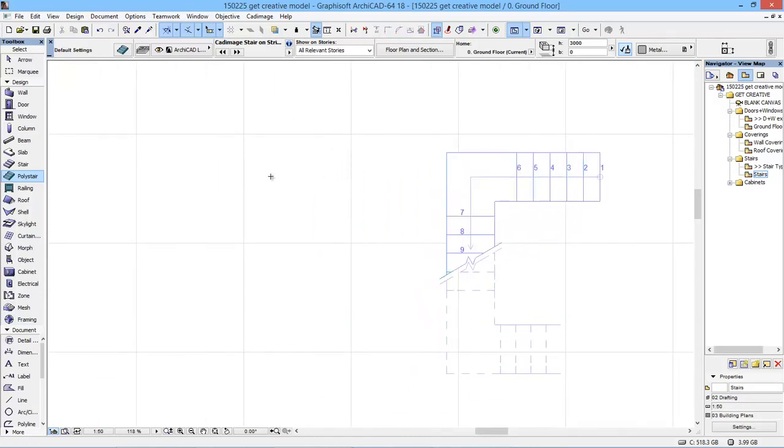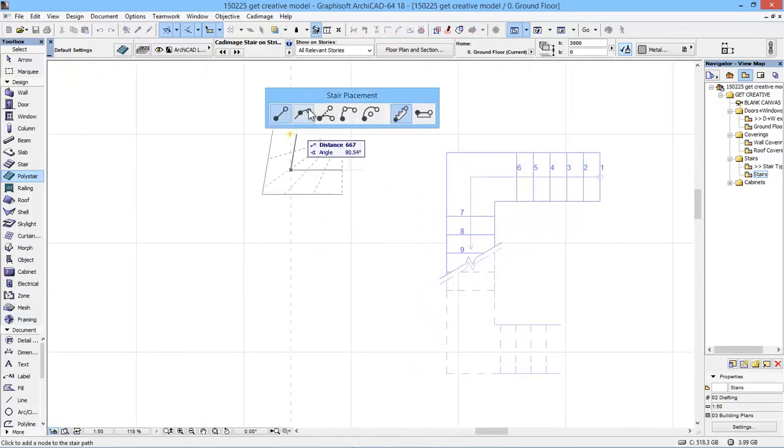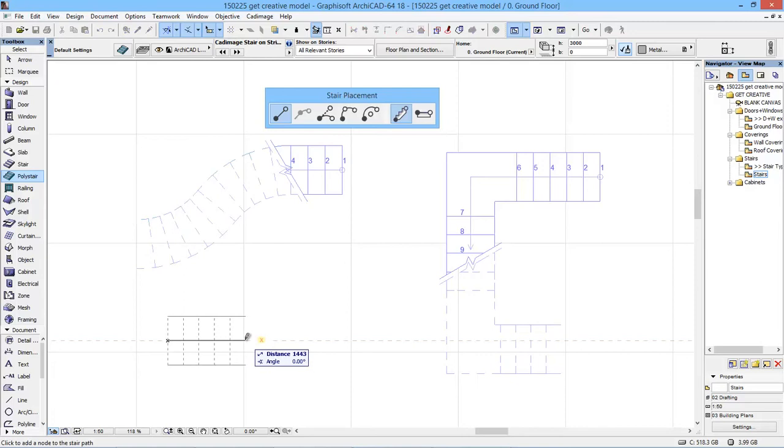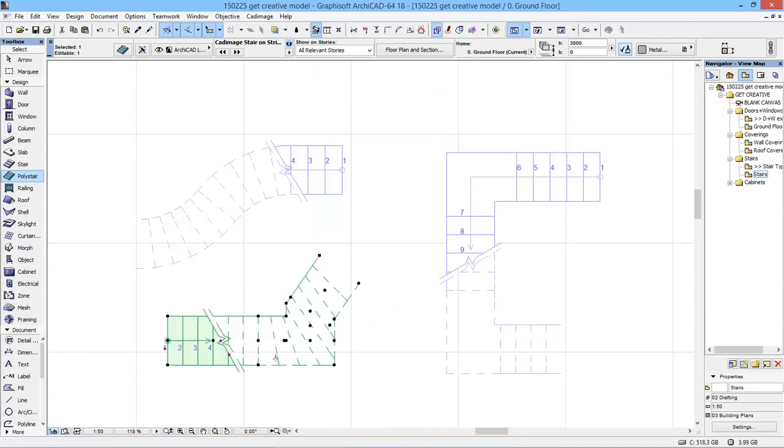Alternatively, if you want, if we just draw another piece, we could start and then we could go into curves and off we go. When we're drawing, if I just draw a straight section and just randomly draw some stuff, if we make a mistake, the backspace key takes us back to wherever the previous point was. We can do a return on here, carry this on, and basic rules like click again at the last point and that closes off that shape.